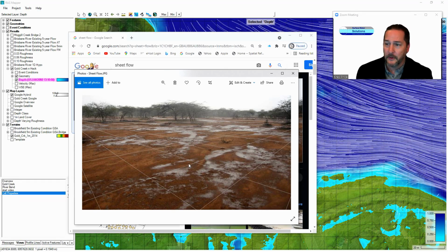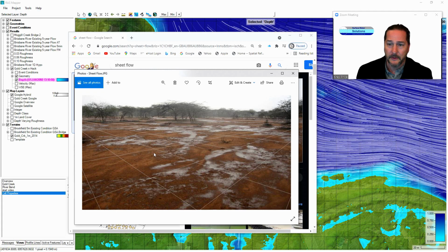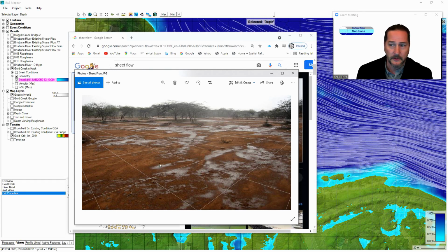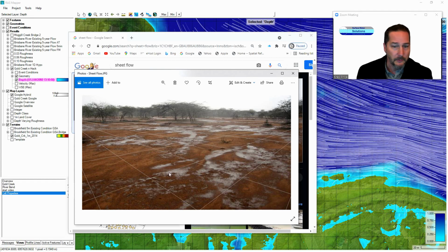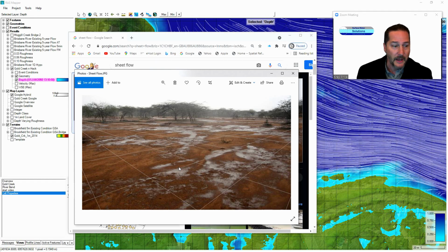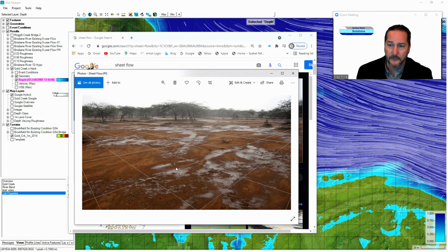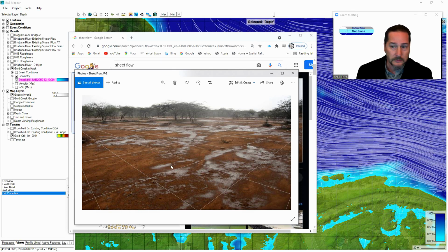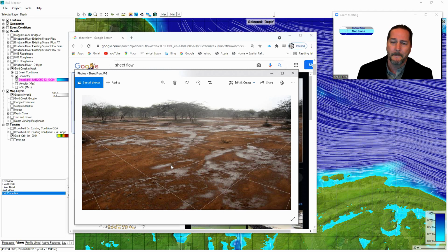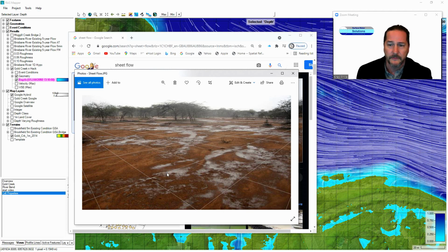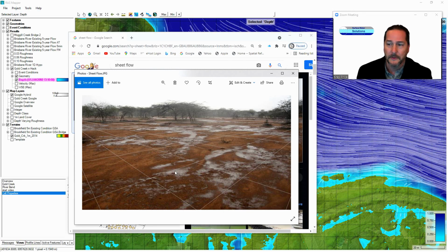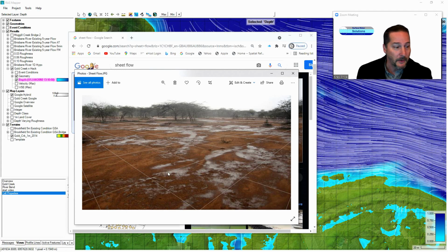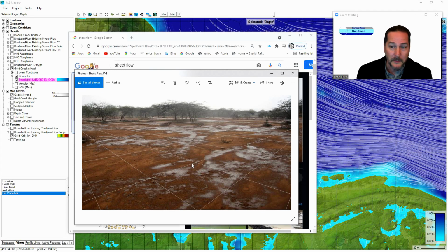Well, if you picture HEC-RAS cutting cross sections around each of these edges and then try to move flow from cell to cell using the energy gradient between the cells and whatever roughness coefficient you've assigned, if your depths are, say, on the order of 1 meter or more deep, well, then sure, your typical roughness values might work. But what about cases where your flow is 1 centimeter deep? Or what if the depth is somewhere near the default display threshold in RASmapper, which is, I think, 1 millimeter?